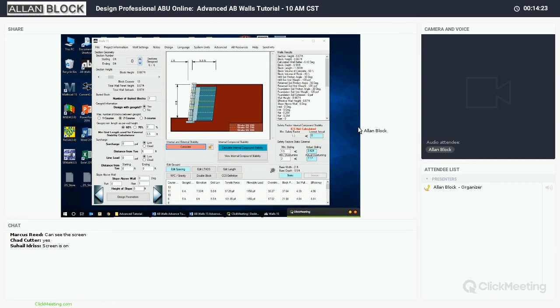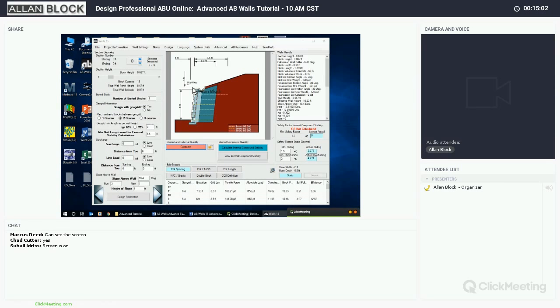And then we're going to go to design parameters, but we're going to bring in that drainage swale now. So we'll keep the cap on. We're also going to bring in our swale. And now when I hit calculate, I should have that 3-to-1 slope and that drainage swale, again being shown on every cross section as we go through. And it's just important. It calls it out. It's no longer just a line on paper saying swale. It is actually being represented in each cross section design too, so it makes it pretty easy.